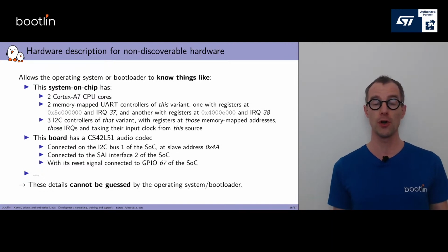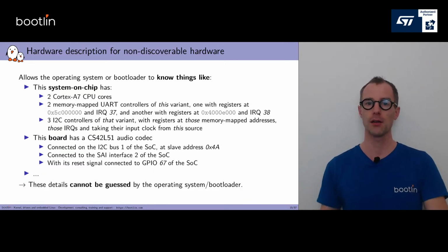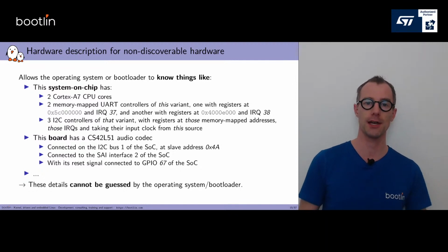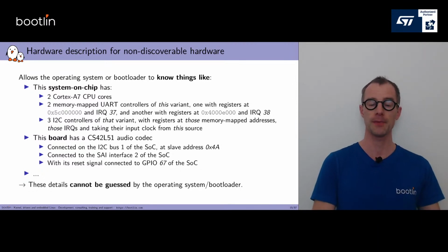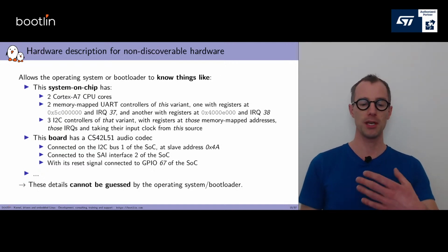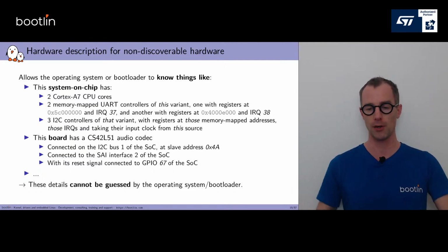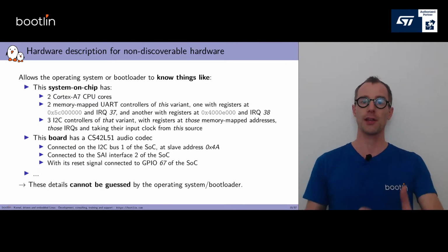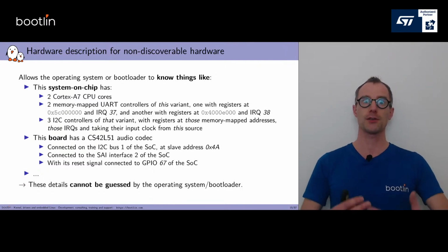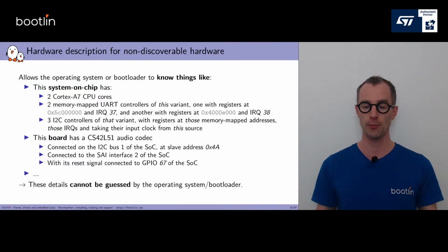And in addition to knowing what is inside the system on chip, we also need to tell the operating system or bootloader what is on our board around the system on chip. Maybe I have an audio codec that is on some I2C bus, so it is connected on a given bus at a given I2C slave address. It is connected to a given audio interface of the system on chip. Maybe it has a reset signal that is connected to some GPIO of our system on chip. And all this connection and integration of our audio codec with the rest of the system needs to be described somewhere so that the operating system or bootloader knows the topology of our hardware.